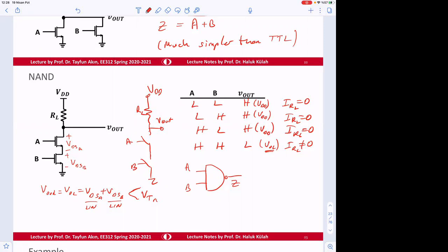It's going to be at the edge of forward active, but you cannot really tell what is happening because this is floating. So let's say this is 0 volt and this is 5 volts, right? So this is off, so this is floating, and you cannot have the voltage appearing here. This voltage is going to be in there, but no current is passing anyway. So we don't really ask you to write the state of the transistor in that case, but you can say it's in the linear mode.